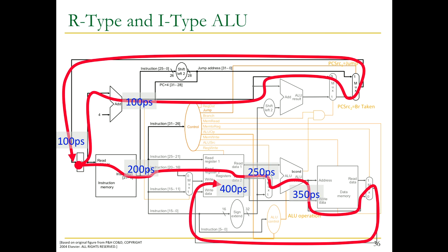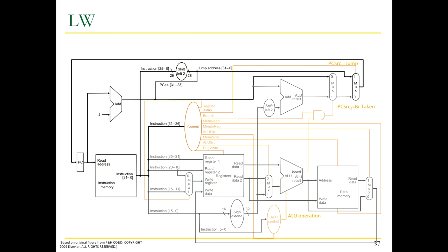There's also an update of the program counter with every instruction, but that's, at least in this case, not on the critical path. In a single cycle machine, that's not on the critical path. That's going to change in a pipeline to out-of-order execution machine. This determining the next program counter can be on your critical path. Now you're saying, PC plus 4, how complicated could it be, right? Well, if it's a jump instruction, what do you do if it's a branch? Okay, anyway, let me not digress. This is 400 picoseconds. That's how you get that.